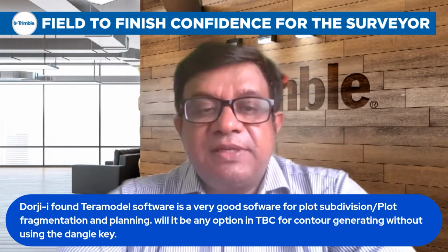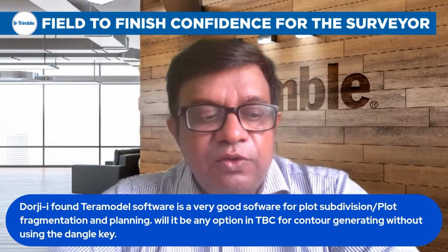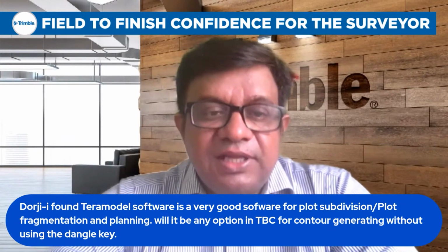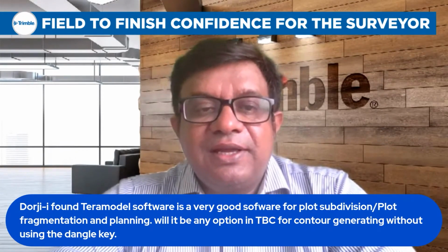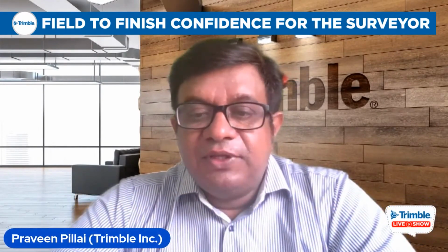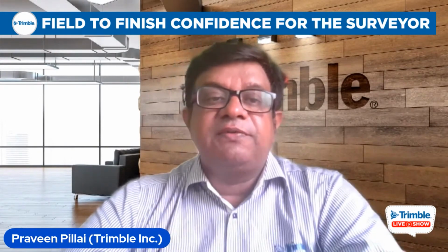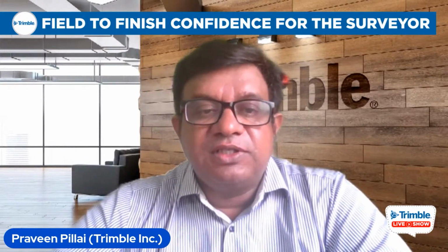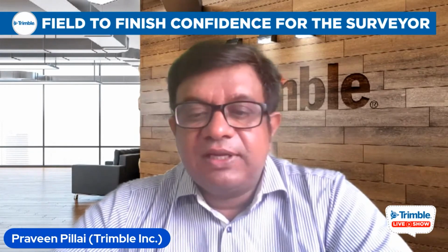But the plot subdivision program has been built into TBC, which I told you already. But you need to have a hardware key. You need a version of TBC which can do this subdivision of plots and tasks, which I have been showing you, in the field itself or in the office. Without a hardware key, without a dongle key, you cannot do that because it's very limited; we have only a viewer version available. So you need a minimum version of TBC software to do a subdivision. We can talk about what version you would require, and we can help you to overcome that.